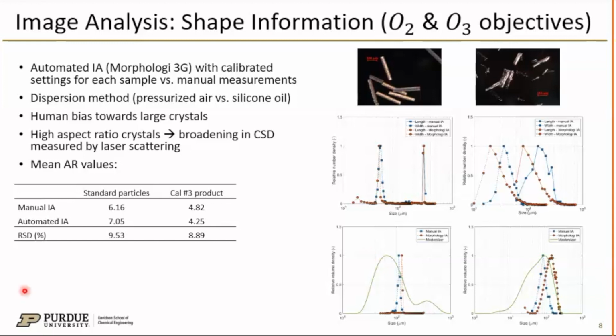For the crystal size and shape terms, we conducted a comparative study by using an optical microscope, Malvern's Mastersizer, and Malvern's Morphology tools. With optical microscopy, we counted at least 250 crystals manually to obtain length and aspect ratio data. Morphology has automated image analysis that can be fine-tuned based on the compound for acquiring the same data for thousands of crystals. Mastersizer was used for size distribution since it is the standard method now used by industry due to its ease of use and fast and consistent data production.